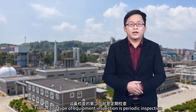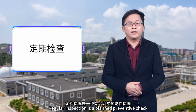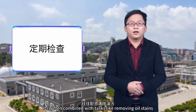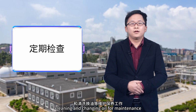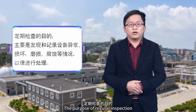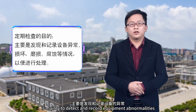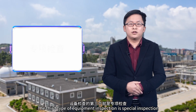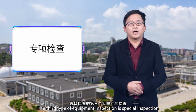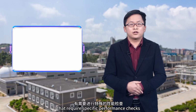The second type of equipment inspection is periodic inspection. Regular inspection is a planned preventive check. It is often combined with tasks like removing oil stains, cleaning, and changing oil for maintenance. The purpose of regular inspection is mainly to detect and record equipment abnormalities, damage, wear, and corrosion for further handling. The third type of equipment inspection is special inspection. Special inspection is carried out when equipment exhibits anomalies that require specific performance checks.